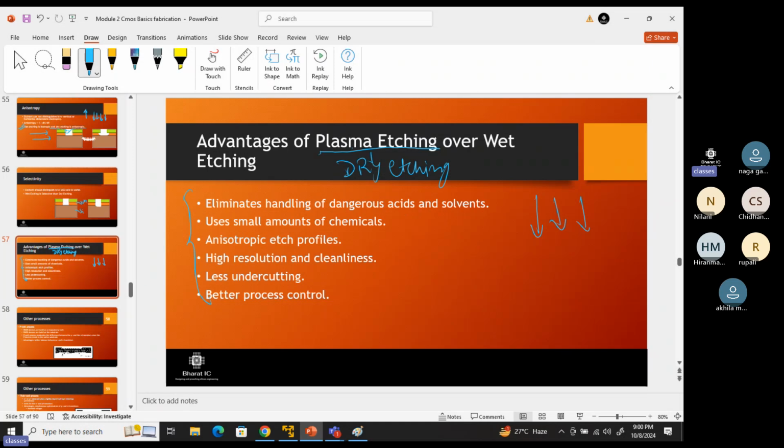Okay. So this is how the overall etching techniques happen. So what etching, how etching is done, what are the types of etching, which etching is much more preferred over that etching, how the wet etching and dry etching are different from each other, how wet etching chemicals react, how dry etching plasma actually reacts. When the dry etching is done, it is done in a vertical way, which is anisotropic in nature. When wet etching is done, it is done in a horizontal way, which is isotropic in nature.